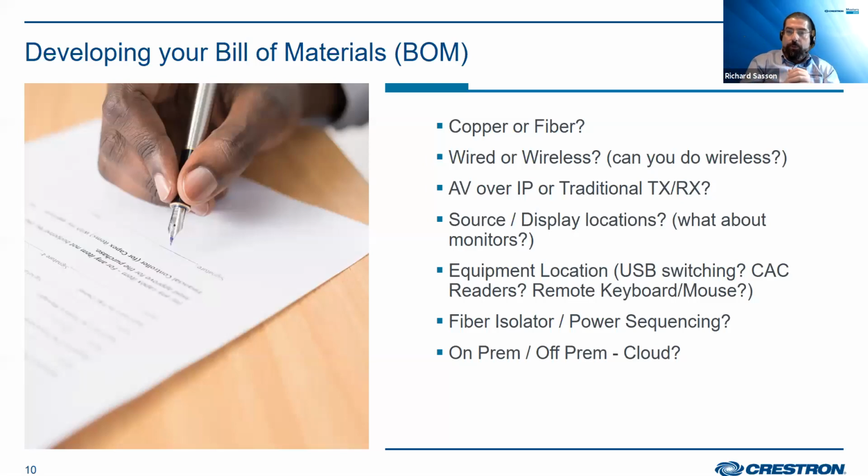So you can do a complete fiber isolation and an air gap solution through that fiber communications concept as well. You can certainly isolate individual NVXs. You can also isolate the switch itself. I've seen recently when people wanted to keep a traditional DM switch, they used NVX for point-to-point fiber for distances that were too far when they wanted to be able to do 4K, for example. So they just switched out to HDMI cards and then just did a pair of NVXs point-to-point via fiber.